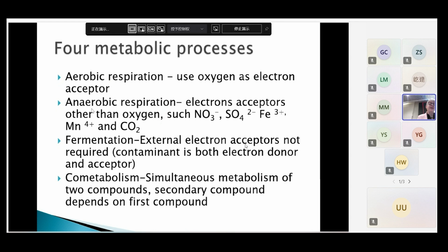So you see pump and treat are quite common, phyto to some extent, bio to some extent, thermal treatments and things like this, chemical treatments, which I'm going to mention a little bit, the soil stabilization and so on. And there are also some bio type of systems like wetlands and so on that are used, and phytoremediation is used somewhat. So it just gives you an idea of some of the techniques that are used.